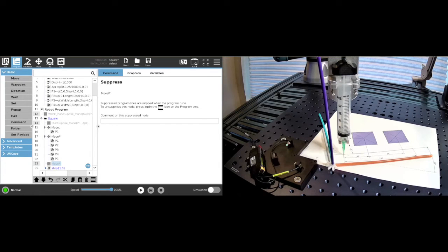Hi. So, if you've been following along with the videos, we discussed the theory of TCPs, the theory of planes, variable waypoints, and how to move the robot relative to the base, the tool, or any plane. So now we're going to put that all together into this concept of a scalable program. And you're going to see how by changing small parameters, we're going to be able to modify the execution of the program and really be able to draw squares in this example all over our plane.